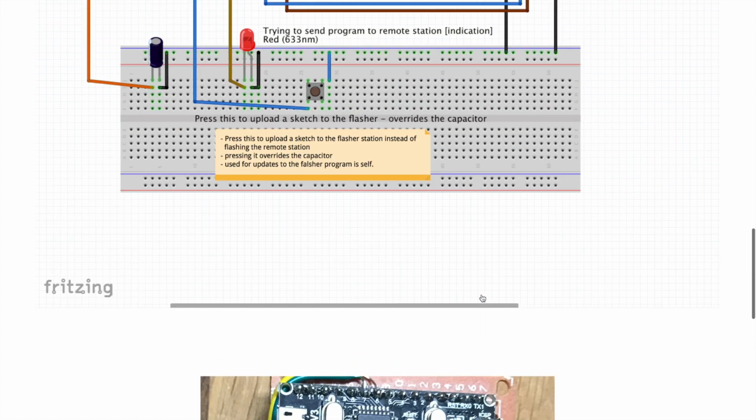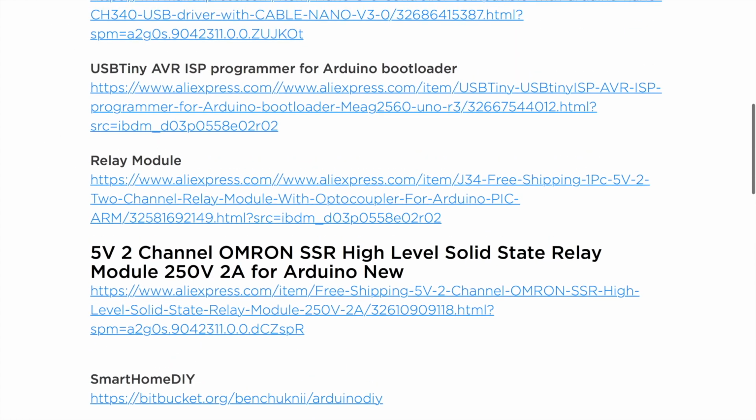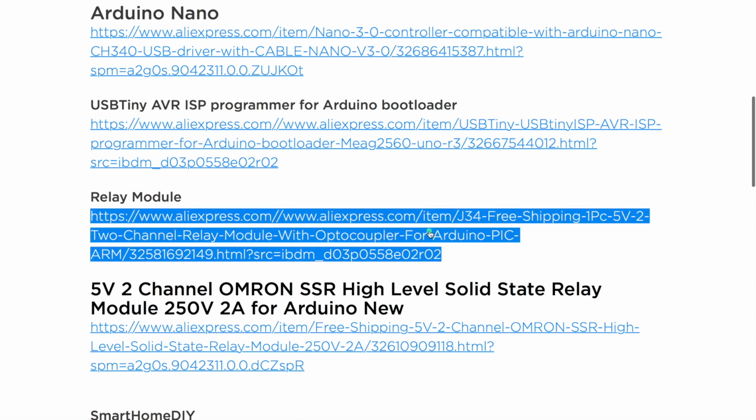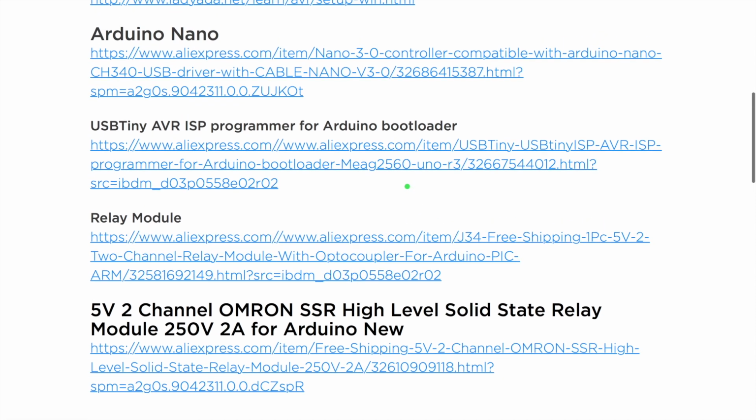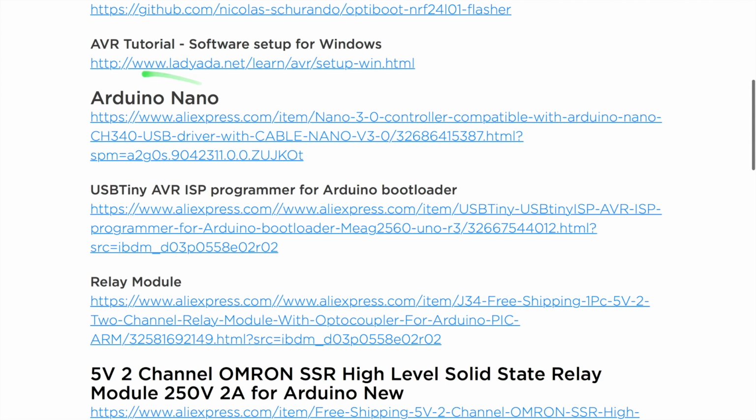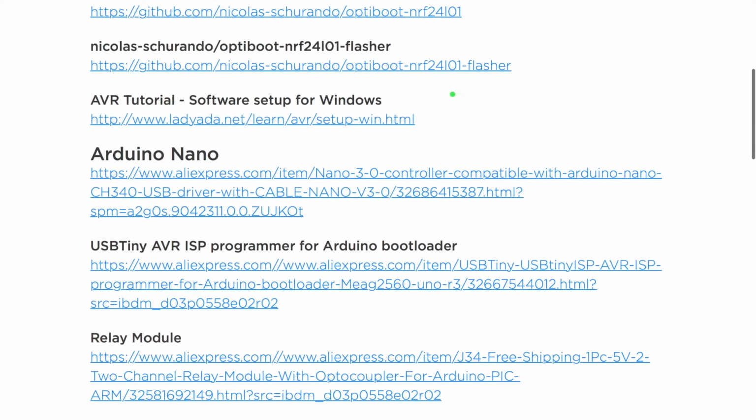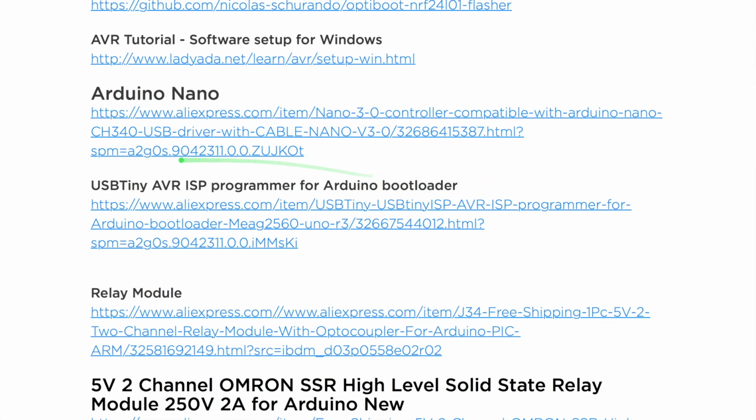You will have a cable for that, and the other side is the computer, and you're going to use a program called AVRDude. AVRDude is just a tool set from AVR where you can do some stuff to the Arduino. You can change its fuses, you can upload a sketch, you can burn a bootloader and other stuff. We won't go into too much detail, but I want to show you how to use it and where to get it from.